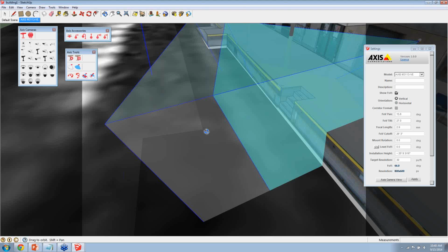We have all kinds of different guidelines under different lighting conditions for what PPF is right to do a job. If you have more questions on that, that's part of our IPVM IP camera course. We can answer all your questions as to PPF there, but for the sake of this conversation, if I know I need 90 pixels per foot to identify faces, I can adjust my camera resolution to get there. In this example, let's say I do need 90 PPF, and I need it right at this stairwell.